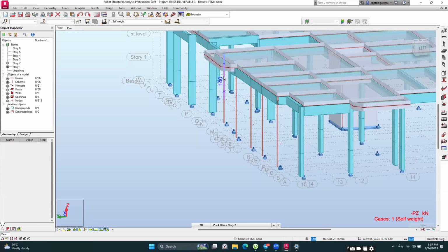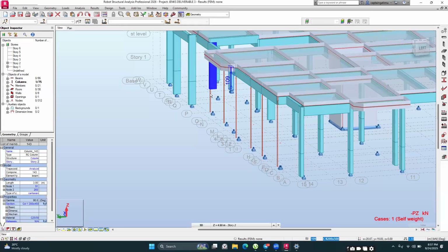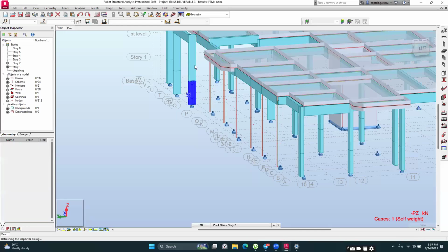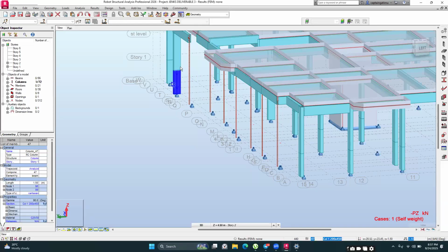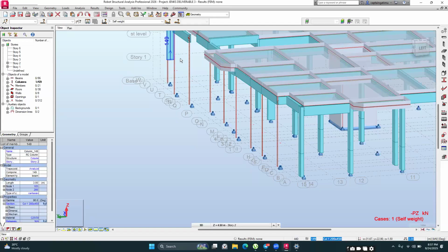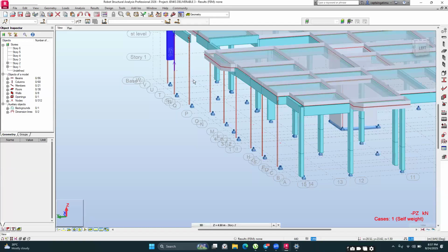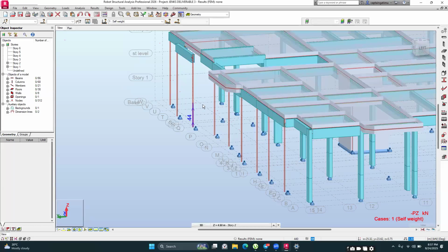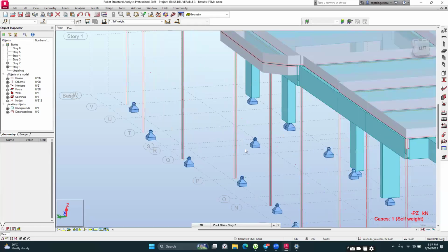From those remnants, you also modeled new columns that hit these elements. The remnants from the cross-sections that were deleted are the ones that do not have properties. So I want you to delete the columns from the areas that are being highlighted, so that you remain with these vertical lines. Let me call them lines because they have no properties.